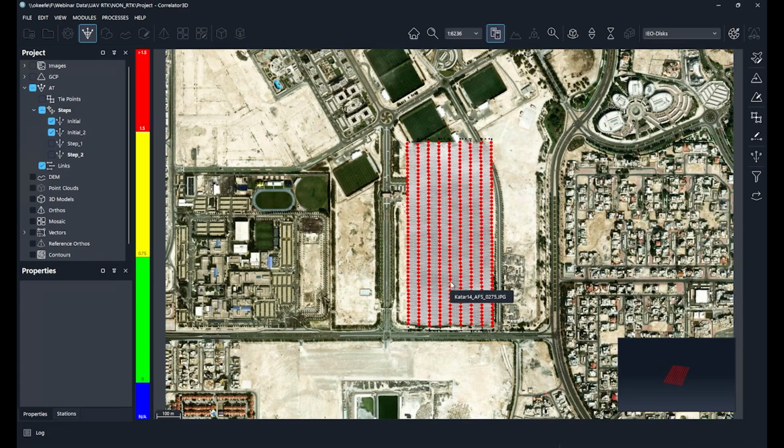The ones you don't want to see are images in blue. That's where you would see a blue disk, which means that image does not have a tie point. What would we do in those cases? Very simple. In Correlator3D we have the option to add a manual tie point through the link creation tool. On top of that, a lot of folks have questions regarding this: what if a lot of tie points are missing because it's dense forestry, and I already did an exhaustive extraction?